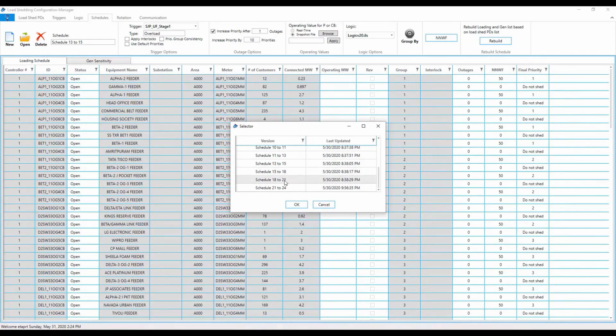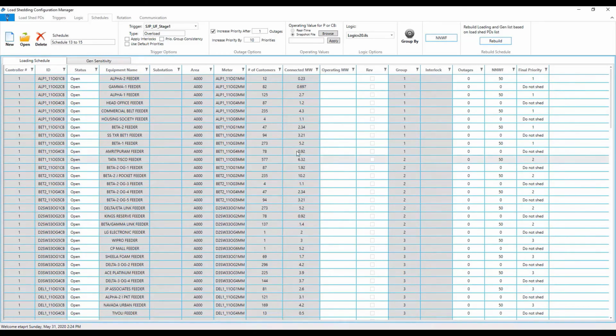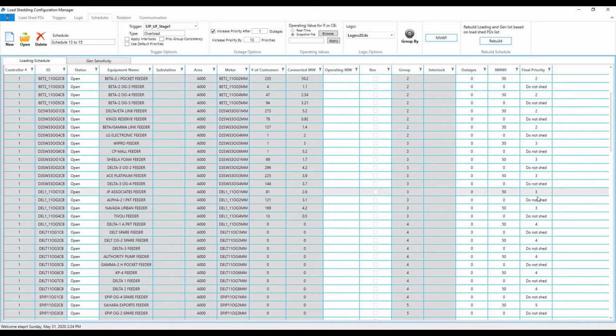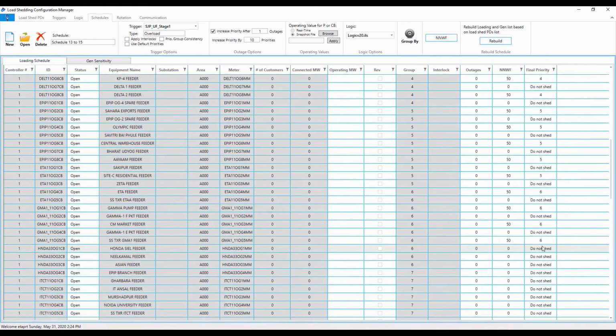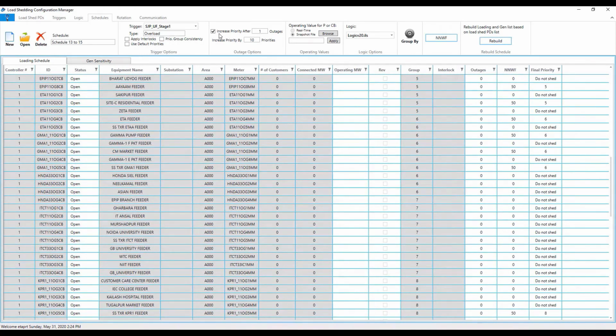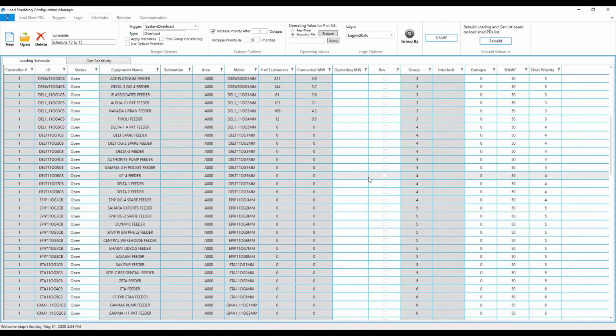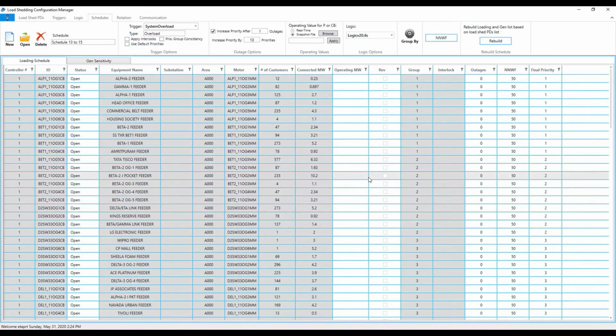the system is protecting. Users can make further changes in this view per event, such as changes in priority after a load shedding event, definition of available power reserves, and final changes on the priority list for a specific contingency event or trigger. Users can create multiple schedules as priorities and logic can change with operating conditions. For example, priorities and logic can vary with operation, such as changes in time of the day, seasons, or unexpected